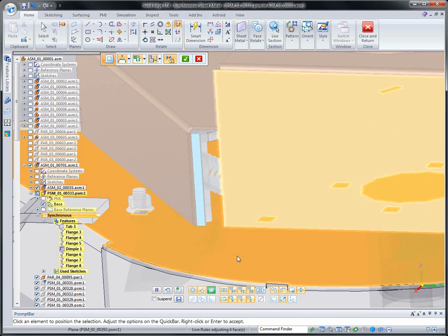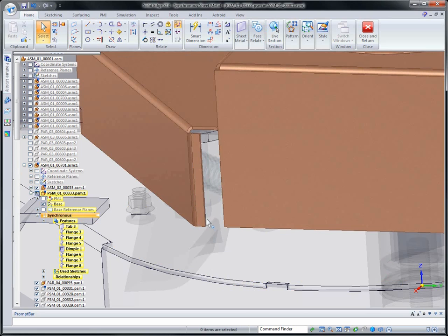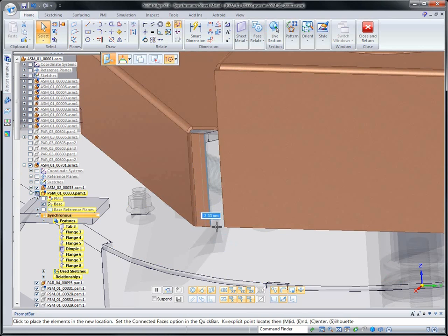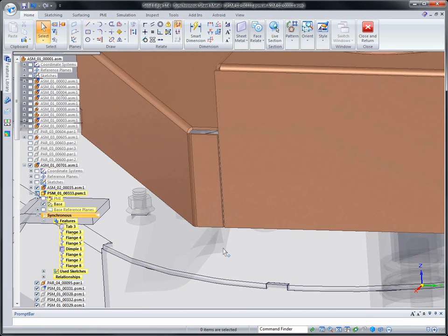With just a few mouse clicks, we can define that the 2 faces are to be coplanar. By offsetting the steering wheel tool from the thickness face 1 mm, we can establish a 1 mm gap between the 2 thickness faces by selecting a key point during the drag edit of the thickness face.